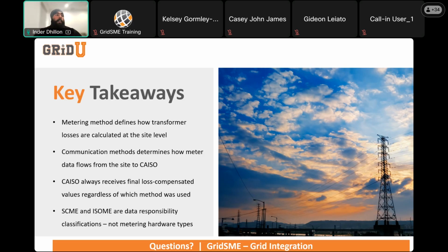Like I was saying, when the BESS controller sends an external BESS idle signal to your BESS meters, they would stop recording any energy being delivered to that meter, and your BESS aux meter would start recording energy that is being used for your BESS aux.